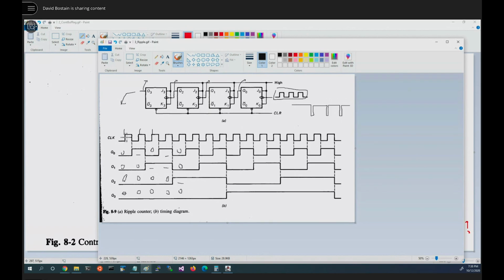But the advantage is no matter what this is, we only are using these falling edges. Because we're using the falling edge and they're spaced equidistant apart, and we clock every other one in the next stage, even if this were irregular periods, this first stage will be symmetrical, 50% duty cycle, as will all the ones that follow. So that's a very good benefit of using a clock.